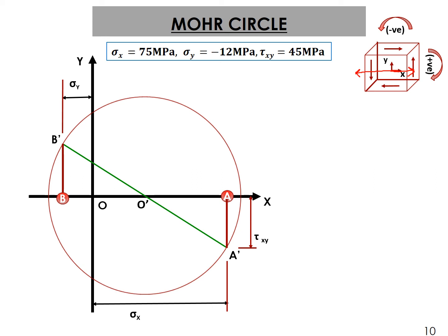So as I told you, either you can draw Mohr circle graphically, or the best part is draw it proportionately and using the given dimension, given lines. For example, this AA dash is tau xy. This OA is sigma x and OB sigma y. So using these given values, if you can find out all the sides, that is of great worth. We can get all the values. We can calculate every parameter, what we have done with the analytical equations.